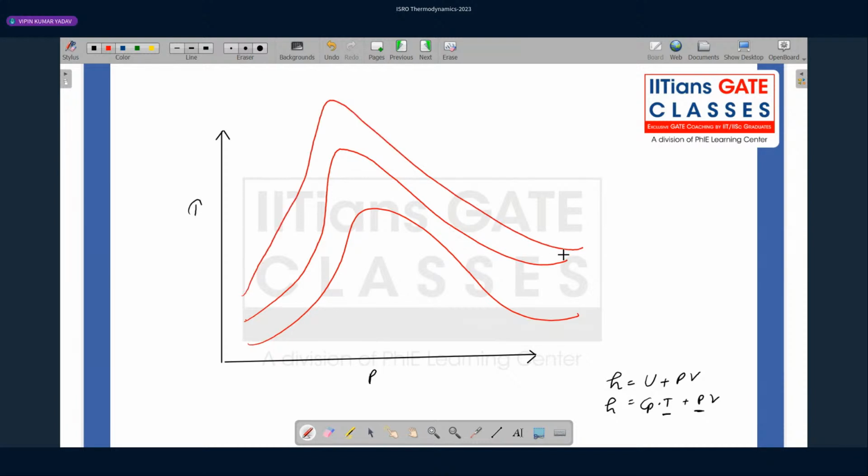And these are all isoenthalpic curves. What do you mean? Enthalpy is constant here; enthalpy is not changing on the curve. For different curves, enthalpy is different, but on a particular curve enthalpy is the same. Now you see this peak where the temperature goes to maximum. If you join all these points,